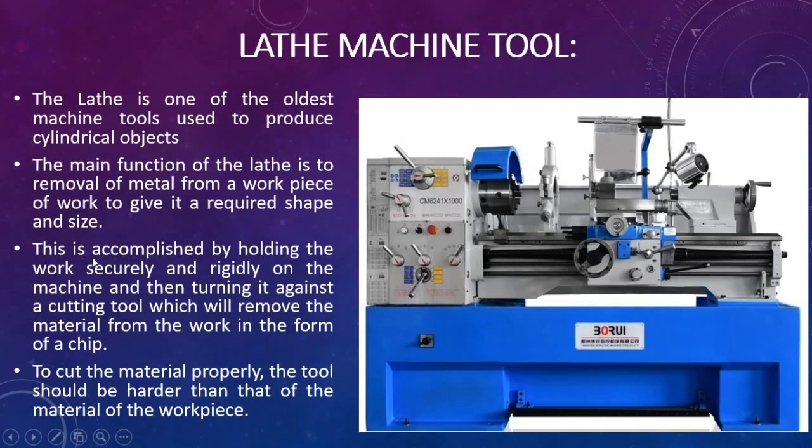This is accomplished by holding the work securely and rigidly on the machine and then turning it against the cutting tool, which removes material from the work in the form of chips. So how is the machining operation done? First we have to hold the work, the job, in a firmly holding device called a chuck. It may be a 3-jaw chuck or a 4-jaw chuck, where you fix the work and perform the cutting operations using the cutting tool.